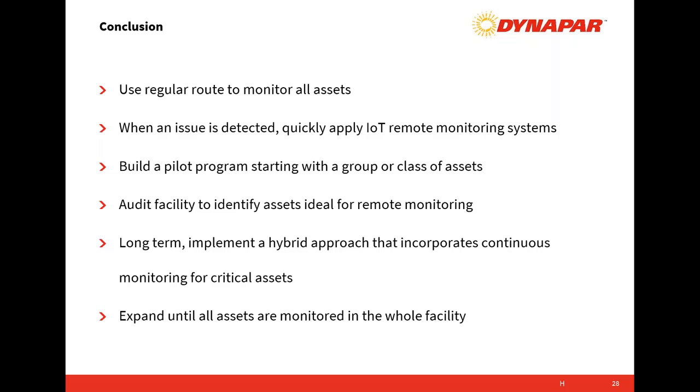The first connection is through email or text primarily. The other option is that the data can be shared with the local DCS or data historian. If they've got an HMI or screen that they're watching from an operator perspective, an alarm flag notification can be shared with the local DCS.